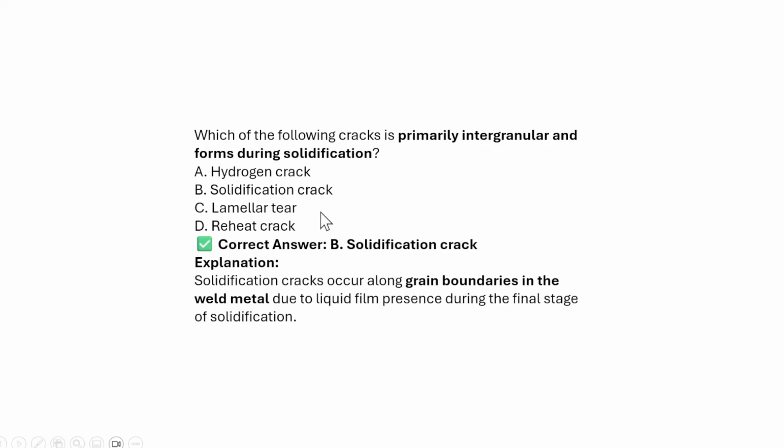Okay, which of the following cracks are primarily intergranular and forms during the solidification? Answer will be A, hot cracking, B, solidification cracking, C, laminar tearing, D, reheat cracking. Answer will be solidification cracking.